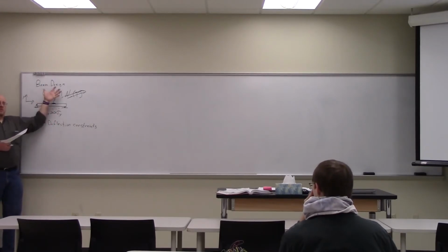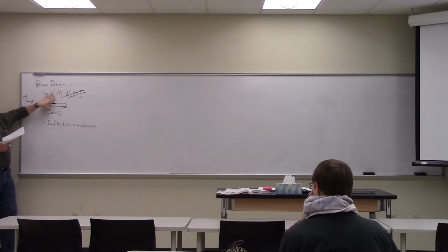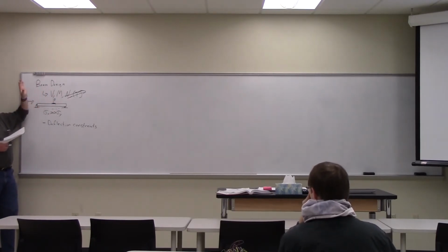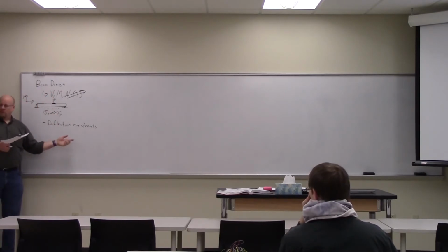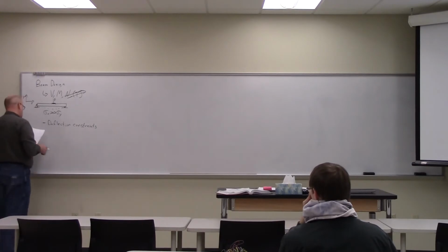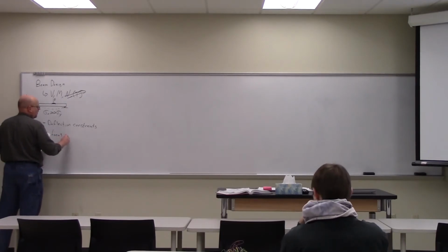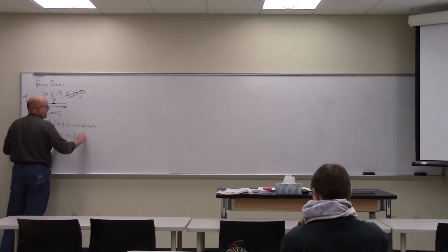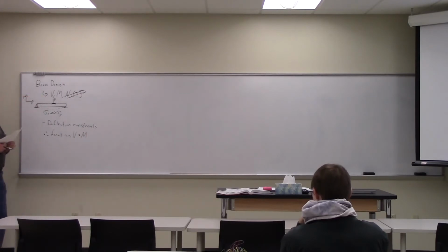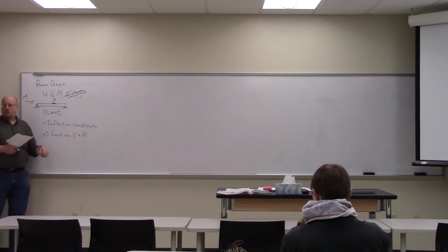Okay, so the point is, the beam design that we're talking about here, in terms of yield or elastic failure of the beam, are not the only constraints, but they're the only ones we're going to deal with right now. So we are therefore going to focus on V and M, the shear and moment elements, in determining our beam design. In other words, we're going to make sure we're designing a beam that can support the V and M.